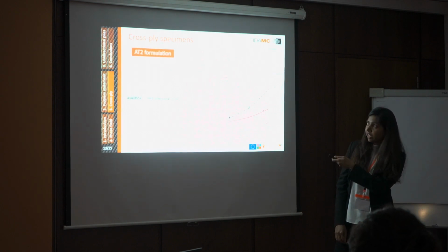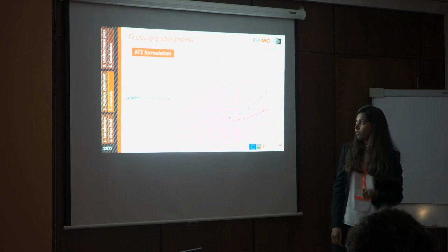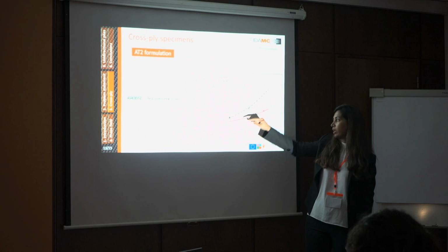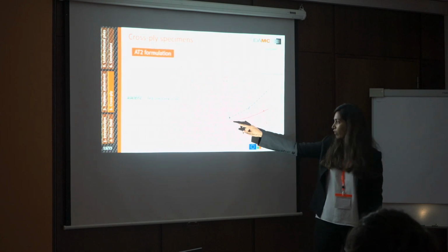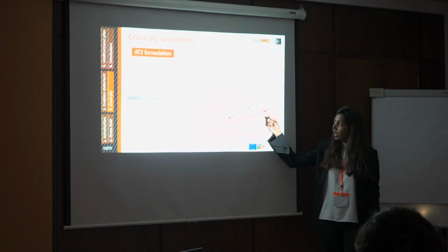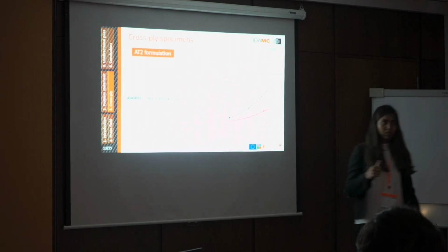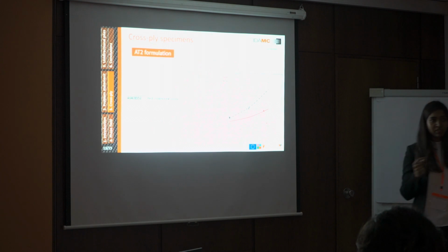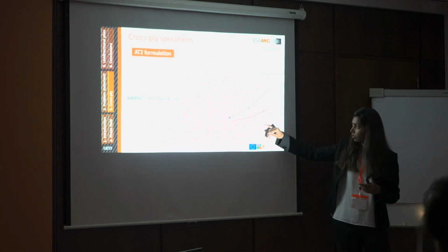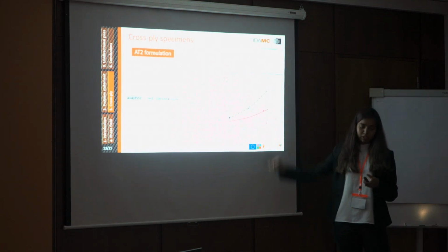If you look at the next formulation, the second formulation, which is 82, here again the failure moments match perfectly well, but not the intralaminar failure. The intralaminar failure from the numerical model is much lower than the analytical model. That is because this 82 formulation doesn't have an elastic domain, and the damage starts in the very first increment. That's why we have this very low curve for the intralaminar failure.